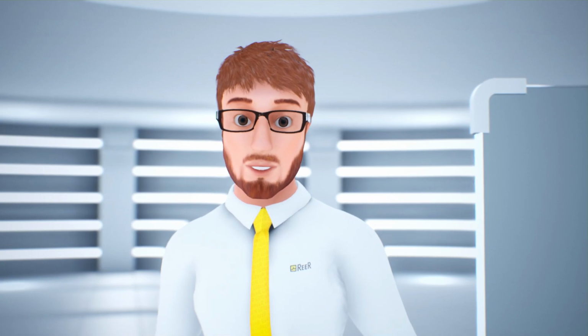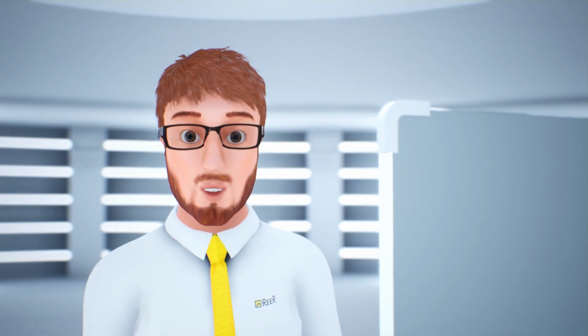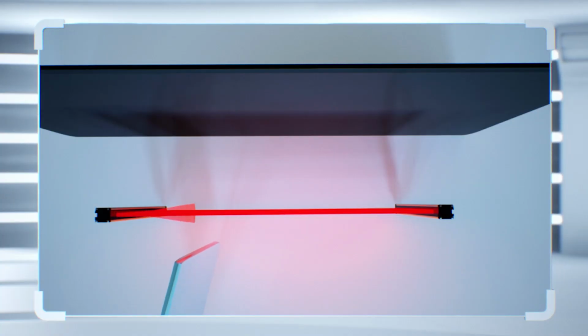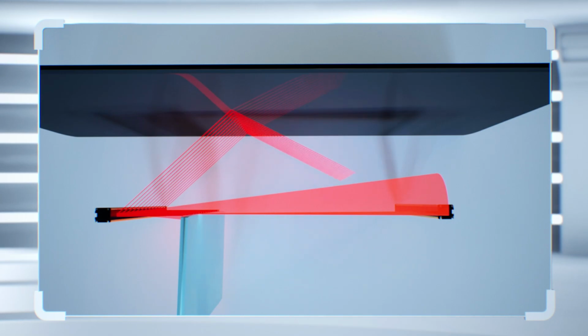We must also consider environmental conditions. For example, under certain circumstances, the presence of reflective surfaces could create an alternative path for the beams, thus preventing the light curtain from detecting them correctly.